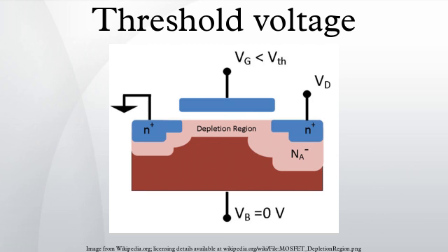Dependence on random dopant fluctuation. RDF is a form of process variation resulting from variation in the implanted impurity concentration. In MOSFET transistors, RDF in the channel region can alter the transistor's properties, especially threshold voltage. In newer process technologies RDF has a larger effect because the total number of dopants is fewer. Research works are being carried out in order to suppress the dopant fluctuation which leads to the variation of threshold voltage between devices undergoing the same manufacturing process.